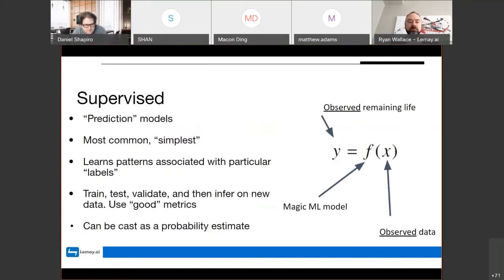And so let's explain a little bit what this magic supervised learning model stuff is. You have some observations from your data set of historical failures and data, sensor data, usage, whatever you pick. Your Y is what you observed in terms of failure. Your X is what you observed in terms of features of the part. And this is going to be specific to some failure mode because you want the model to be somewhat specific, not just, in general, are things going to go bad?